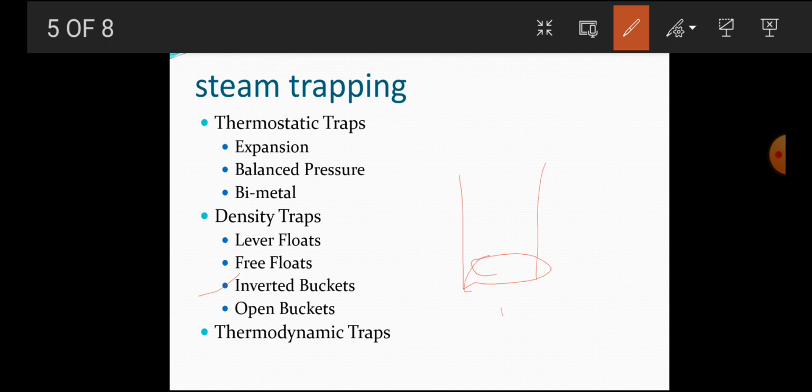It gains buoyancy to close the valve when steam or air enters. They open by the combined effect of levering of the bucket and cantilevering of the valve block.